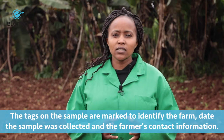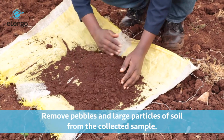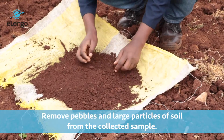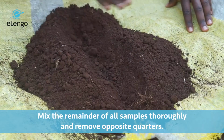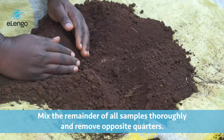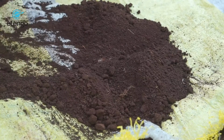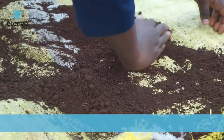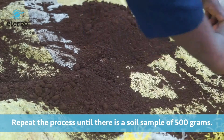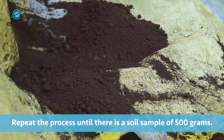The soil collected in different sample areas is placed in a sack. Pebbles and large sods of soil are removed. Later, the soil is mixed into a homogeneous mixture. The soil is divided into 4. 2 opposite quarters are eliminated. The soil is later mixed again into a homogeneous mixture, divided into 4, and later 2 opposite quarters are removed. This process should be continued until we get a sample size of about 500 grams.